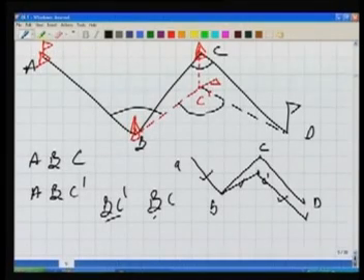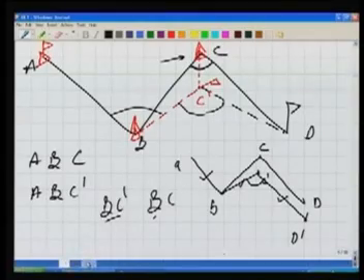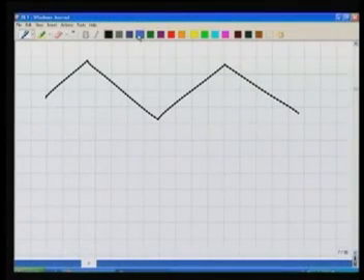Now what has happened here? Because of the miscentering of this ranging rod, and because now the theodolite has no miscentering, the miscentering was only of the ranging rod. This angle at B has been measured wrongly, and because of that the point C dash shifts here. Even if this angle BCD is measured correctly now, we are plotting this BCD here, so our point D shifts here to D dash. So finally our actual traverse was like this, but now after the plot our traverse gets shifted.